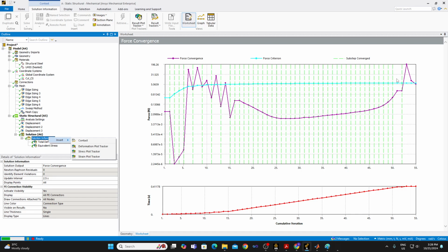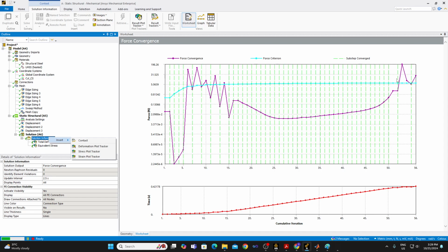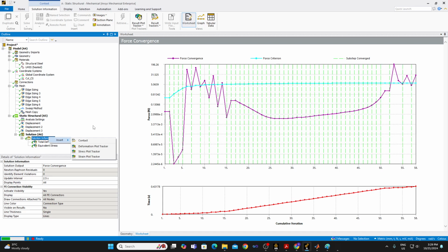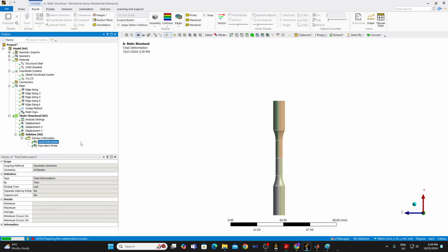But we would be able to simulate the ultimate stress points because it's a displacement controlled solution. That means all we have applied is displacement. We have not applied any force. The force is the response to the displacement. Once the solution is complete, we would be using a probe to track the reactions as well. But right now I believe it is encountering ultimate stress. So necking should start forming now.